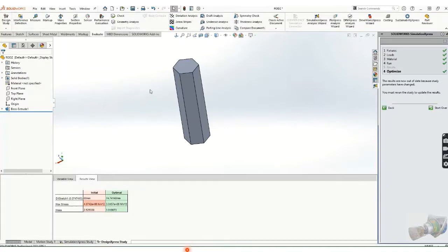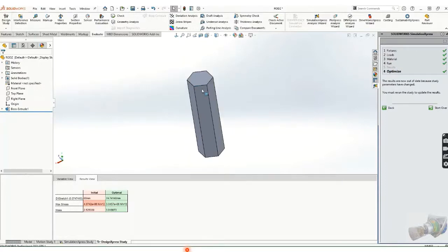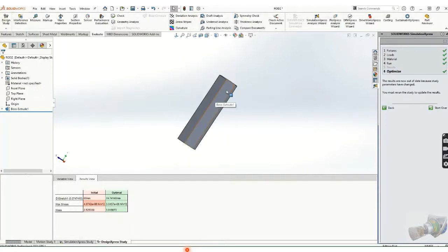So instead of carrying out multiple calculations, you have got directly that if you go with a 75 mm size of the bar, the stress will get reduced, but at the cost of what? The increased mass. You can see the mass has increased by almost 1.5 kg. So you have to take this into consideration also, because the cost has now increased.